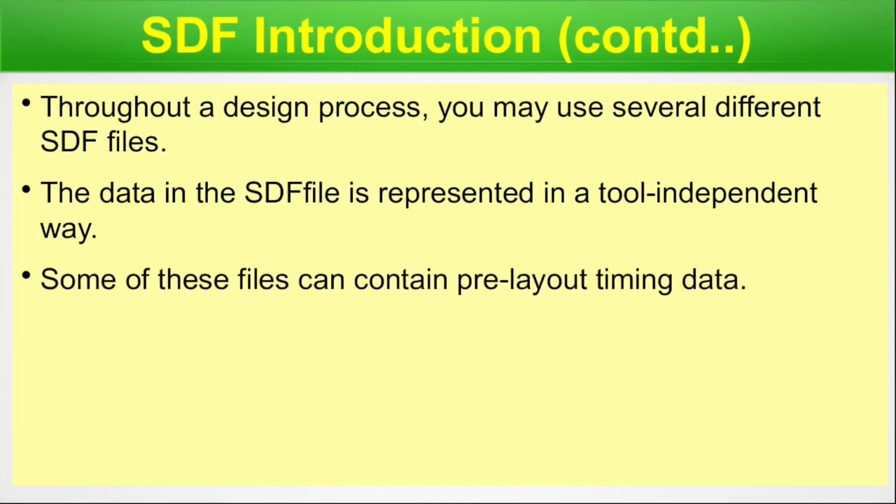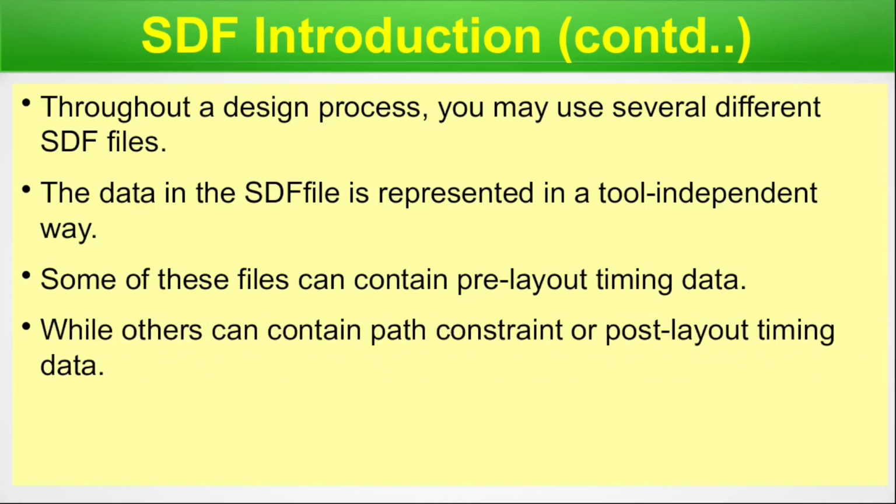Some of these files can contain pre-layout timing data. As I have already mentioned, if it is generated from the synthesis stage or from the pre-layout STA, then obviously it will contain the pre-layout data. If it is generated from the post-layout STA or PNR stage, then it will contain the post-layout data, while others can contain path, constraint or post-layout timing data. So this depends on the stage from which the SDF is generated. Whatever data is unique to that stage will come into the SDF.